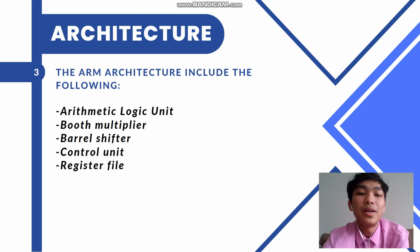The next one is Barrel Shifter. The ARM Arithmetic Logic Unit has a 32-bit barrel shifter that is capable of shift and rotate operations. The second operand to many ARM and Thumb data processing and single register data transfer instructions can be shifted before the data processing or data transfer is executed as part of the instruction.